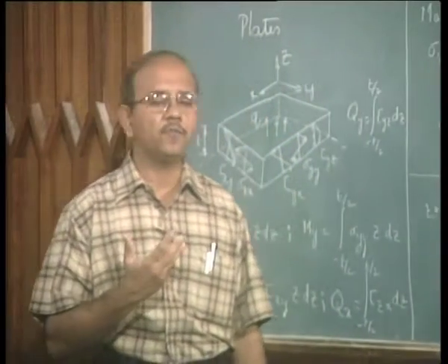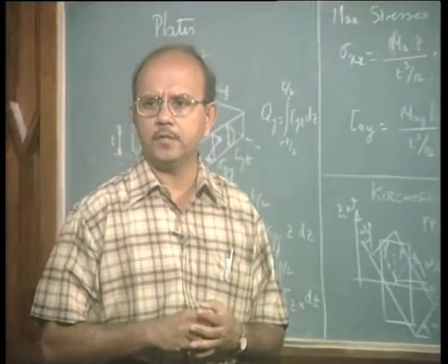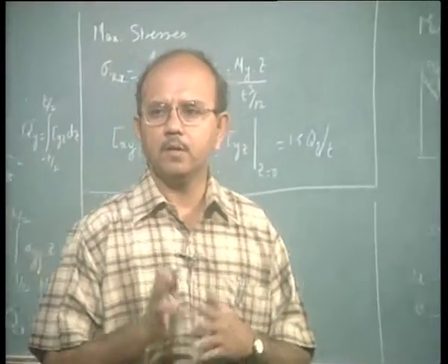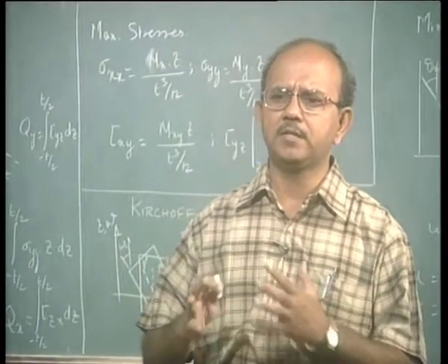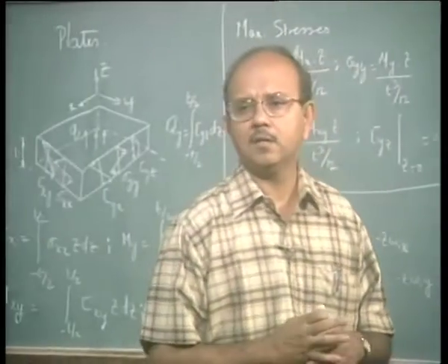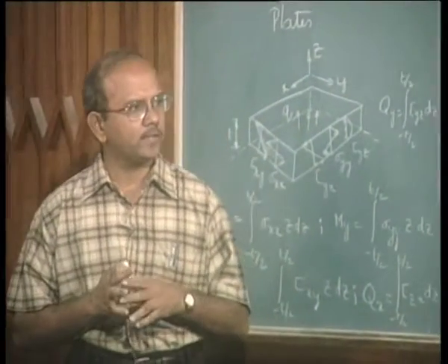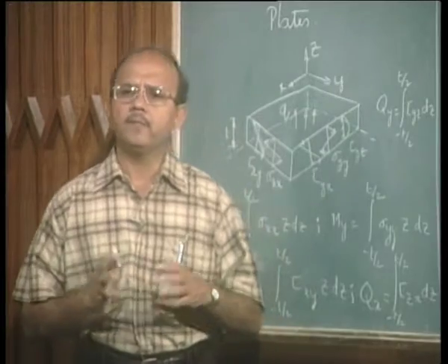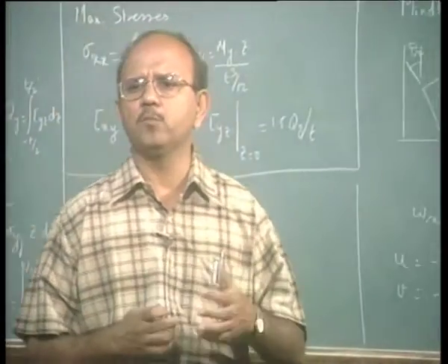plates and shell elements. In fact, in today's atmosphere of the commercial software that is available, many of them at least do not distinguish between plates and shells separately, and they call this a plate shell element. There are reasons for it, we will see why this is so, but plate shell elements are one of the most difficult elements to formulate.